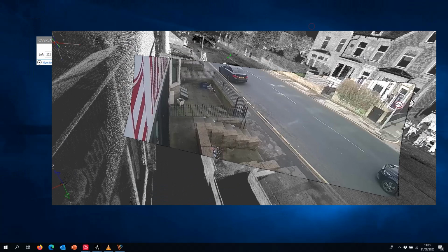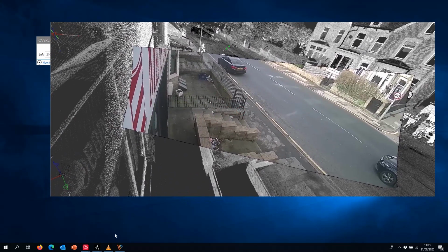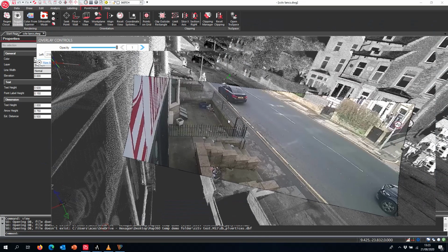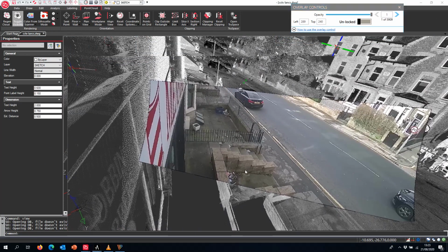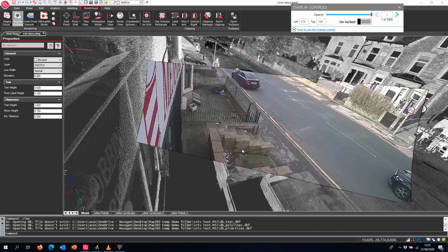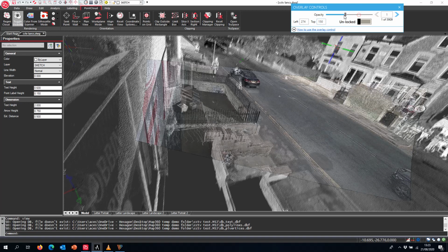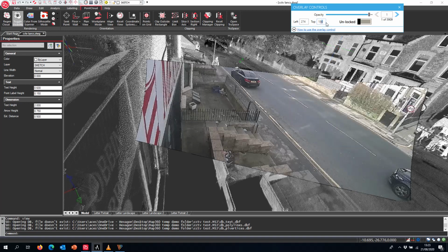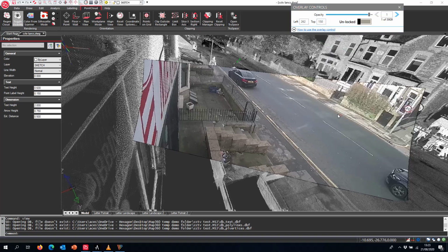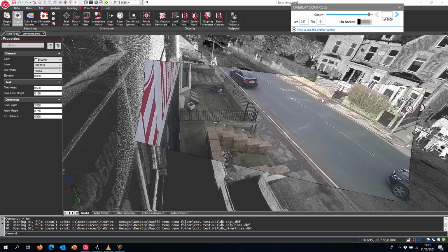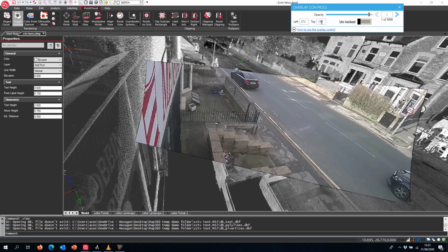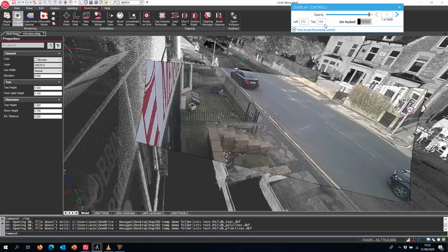And all we have to do now is line up this image frame with the view in Map360, which will, not surprisingly, match the area where the screenshot was taken. But this can be adjusted even pixel by pixel if I wanted to. So if I go here on 150, you can see that the image moved 5 pixels up. How much you actually wanted to move it? 5 pixels down. Sorry. And we can adjust this until it's correctly lined up.